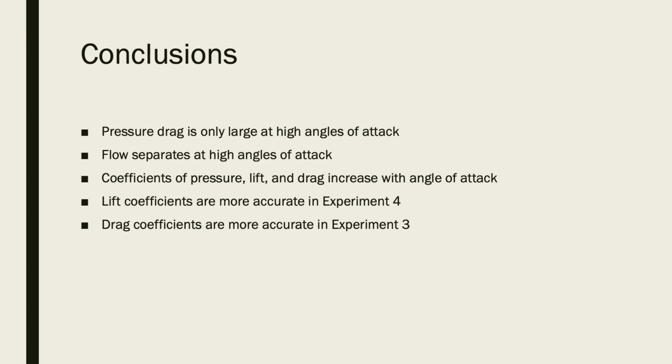This is likely because the wake deficit method used in experiment 4 is more sensitive to instrument error, since the velocity distribution must be carefully measured with the anemometer. However, experiment 4's comparative success with measuring the lift coefficient means that it remains a valuable lab procedure and that careful drag measurements can be standardized in the future.